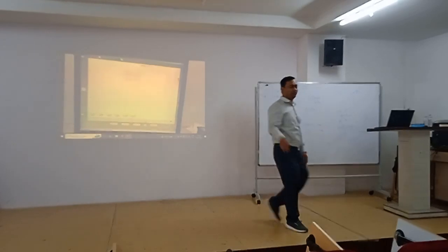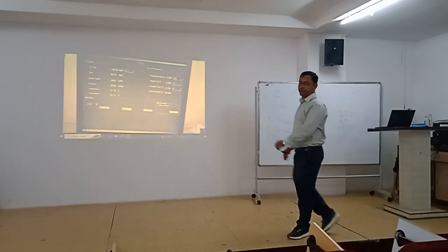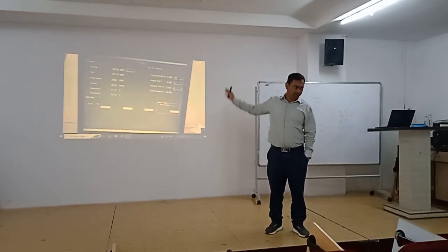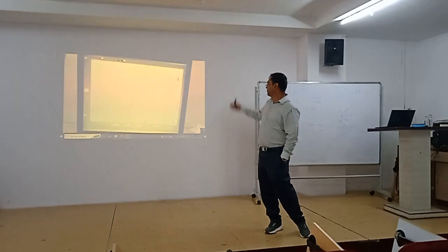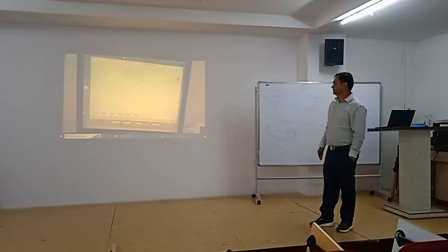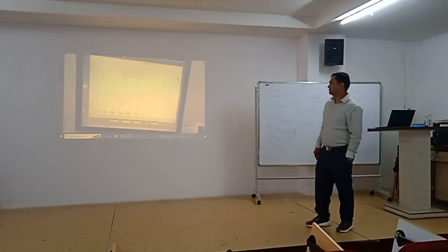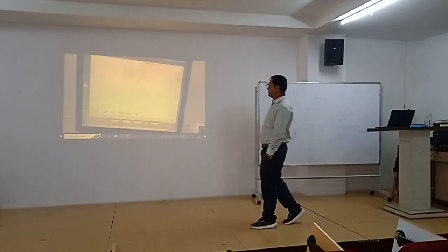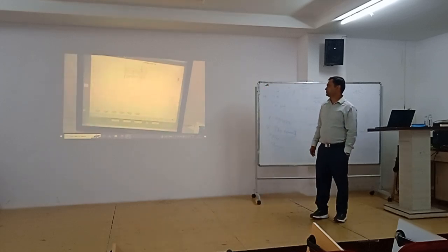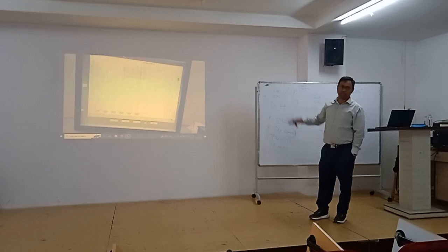So why it's not coming? Because the value of PID gains what you have said is not proper. So you have to tune the controller. So that's why we are changing some of the parameters in the controller. So still it's not achieved to the desired value. It keeps on varying.